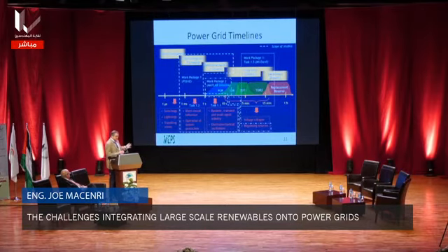Okay, now moving to some of the challenges that we have. This is a timeline, a logarithmic timeline, going from microseconds up to 1 hour. Essentially, power system engineers, when designing and operating power systems, have to look at this entire timeline. So when we're down at microseconds, we're at various wave phenomena, such as lightning-induced transients and switching-induced transients. Then from 1 millisecond up to 1 second, we're into electromagnetic transients, and then electromechanical transients, then from 1 second up to 10 seconds.